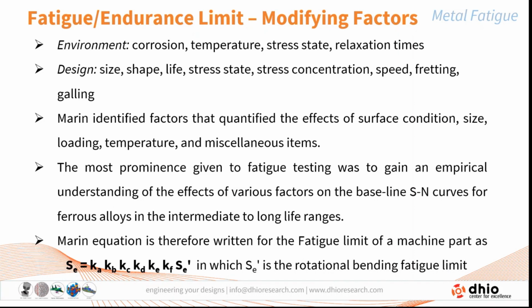So for all these conditions, Marin identified the factors that quantify the effect of surface conditions, size, loading, temperature, and other miscellaneous items. The main prominence given to fatigue testing was to gain an empirical understanding of the effect of various factors on the baseline standard SN curves, which are available in the data handbooks for most of the standard materials. So for any materials other than the standard ones, one has to look into these aspects.